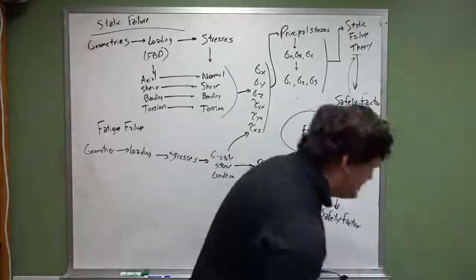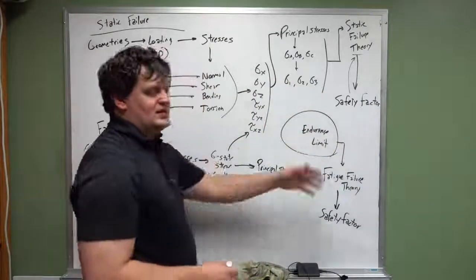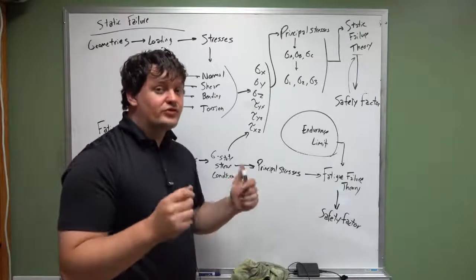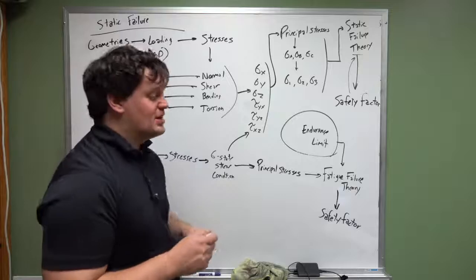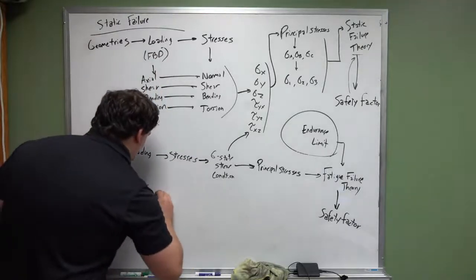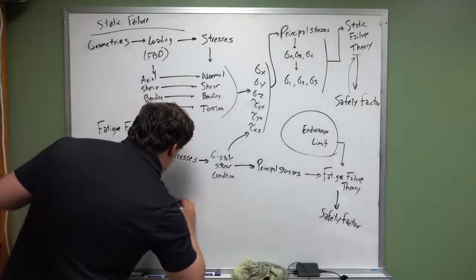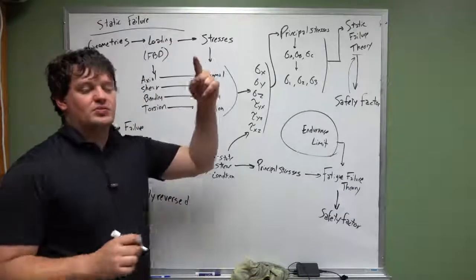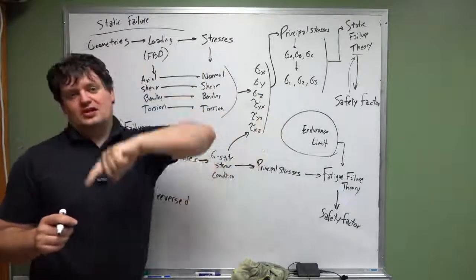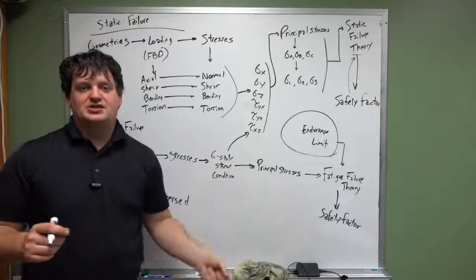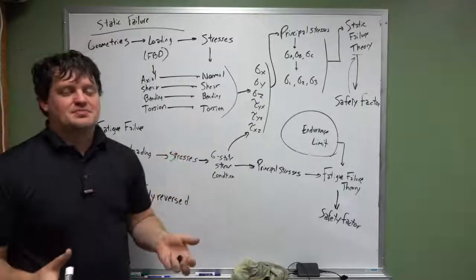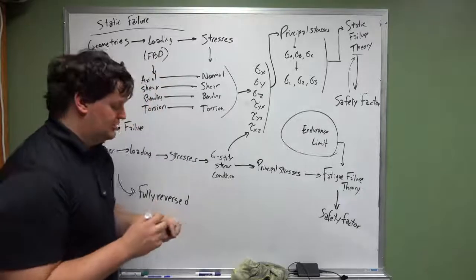But for all of the discussion that we've had so far, this assumes a fully reversed loading. Okay, so keep that in mind. This is fully reversed, which again means your stress element goes from tension all the way down to compression, all the way back to tension. It's a fully reversed cycle because it experiences the same magnitude of tension and compression loading.